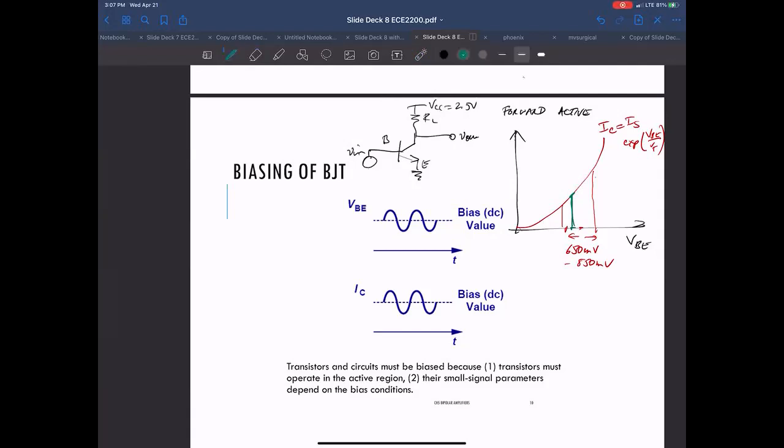In the past, we've said, okay, our signals are small, our V input signal is, in the case of a microphone, say 10 to 20 millivolts. And we just drew this battery here. We said, okay, this battery is, I don't know, we just threw out numbers, 800 millivolts. And here you go, we've biased the amplifier.